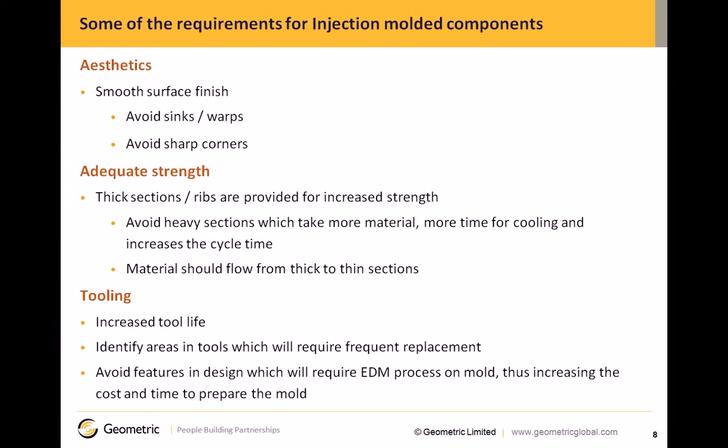To ensure that we have an increased tool life, designers must avoid features which will require EDM processes, which take time and also cost a lot more. These are just some of the areas which we need to concentrate on to have a good plastic product or a good injection molded product.